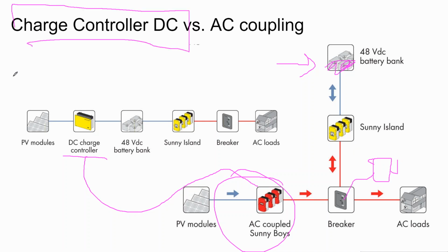DC coupling will win the theoretical, technical discussions, and as the industry moves forward, we should see DC coupling become more of the standard practice. But right now, there's more opportunity for retrofitting existing solar arrays with batteries than there is selling new solar arrays with batteries.